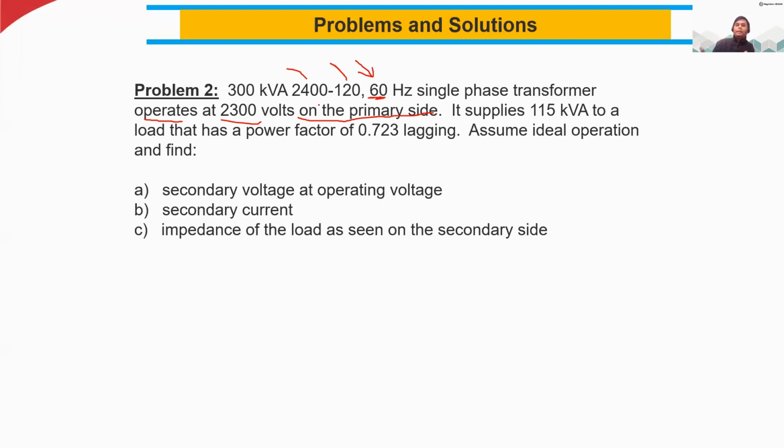So you should remember capacity. We always design the machine for a certain capacity, but in practical application it works with different loads and gives a different power output. So we calculate the efficiency in terms of output divided by input, right? That is a very standard formula for efficiency. For example, let's take this transformer. We have 120 volt, that is the VS secondary voltage.